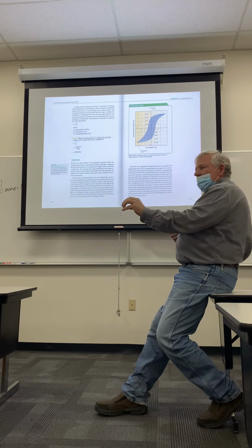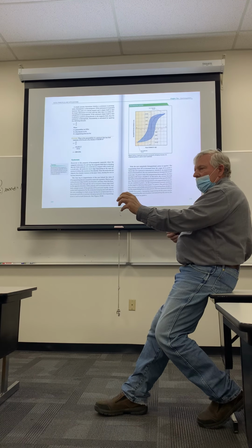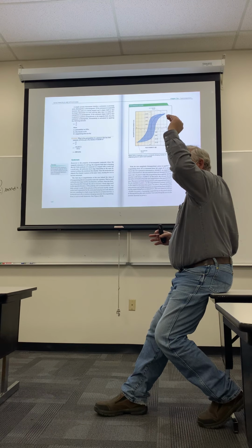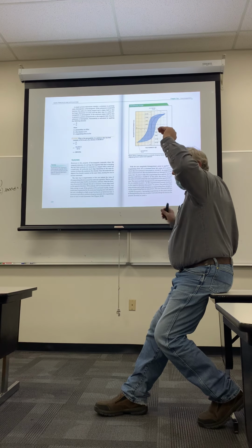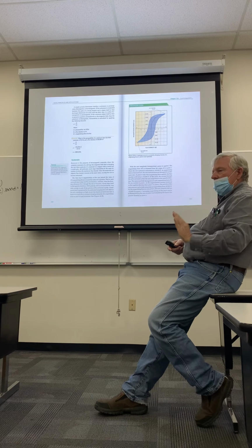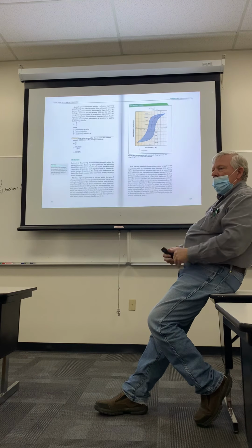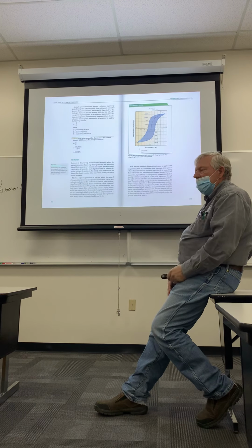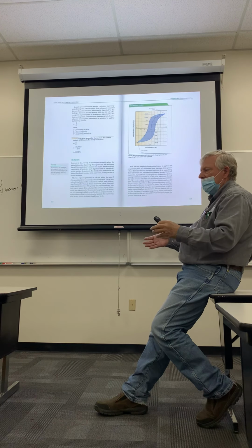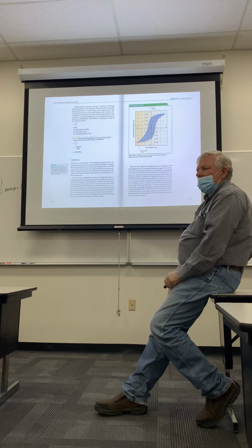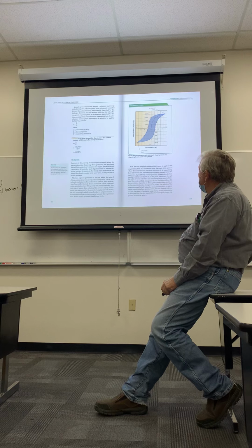You induce current into an electromagnet, and it takes a second to ramp up to full saturation. And then when you turn the power off, it has a tendency to lag behind and slowly give up its magnetism. That's retentivity. Retentivity is a function of a material to resist giving up those lines of flux, which is another word we're coming up to here in a minute.